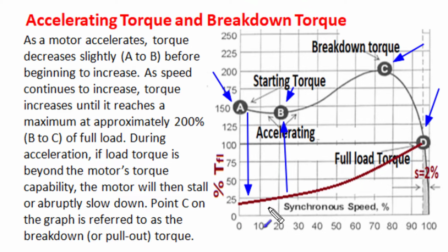And if a motor has a heavy load start and that heavy load requirement is more than the starting torque produced by the motor, then in that case the motor will not start and will remain stalled as it is, and such operation for a small duration, drawing enormous stall condition current, may damage the motor winding. So one has to ensure that for smooth acceleration and start, the motoring torque must be more than the load torque